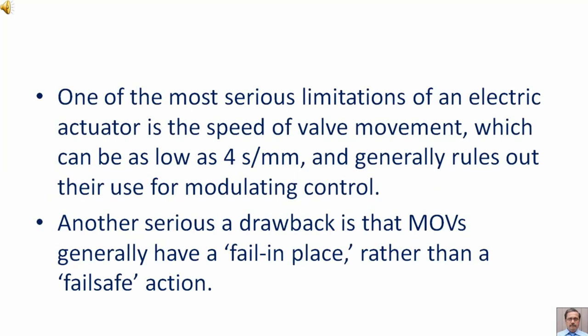One of the most serious limitations of an electric actuator is the speed of valve movement, which can be as low as 4 seconds per millimeter and generally rules out their use for modulating control.